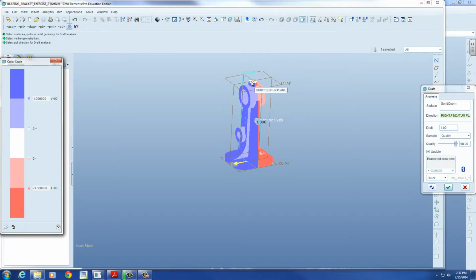It's looking pretty good, but we need this flat surface drafted, don't we? If we don't put an insert in there and pull it out, we're going to put an insert in there and pull it out, so that has to be flat. Because that insert is going to shut off on that tool right there and pull that pin out of the top. So that's going to be flat.